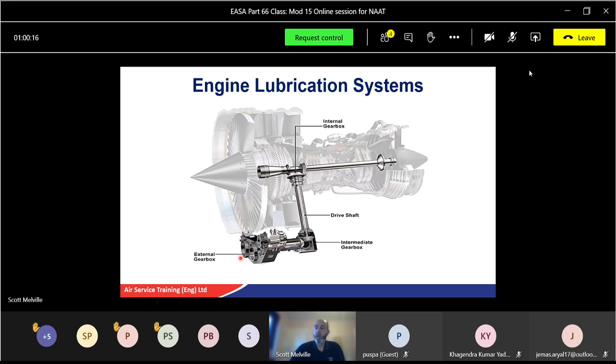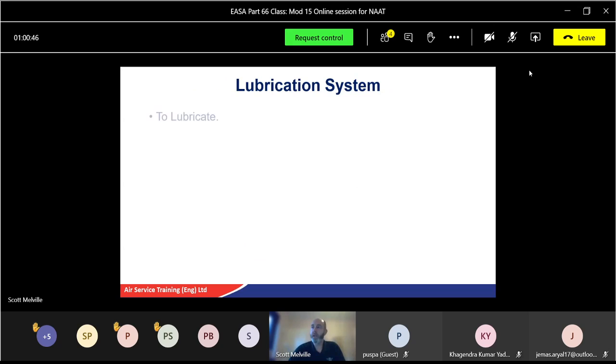But in the gearbox, you have lots of gears, lots of moving bits. You'll have your starter motors attached to it, alternators, fuel pumps, your RPM gauge, the tachogenerator, all these getting driven. Well, if there's no oil in there, they won't drive for very long. So we're going to look at the oil system, oil pumps, and how we get the oil to all the bearings and all the rotating parts in there, and how we control that oil. So the oil system, as said, lubricates and makes sure it's fed with the correct oil, nice clean oil, and the right viscosity and that sort of thing.